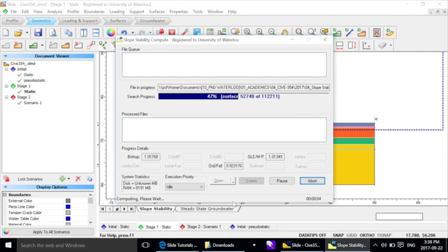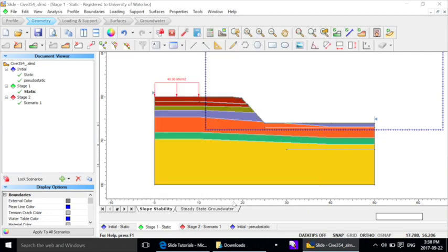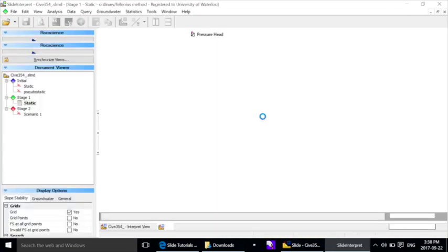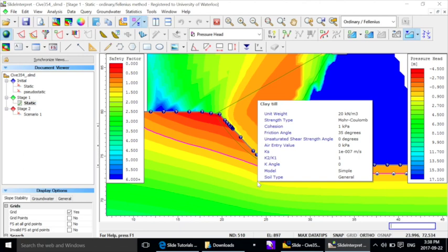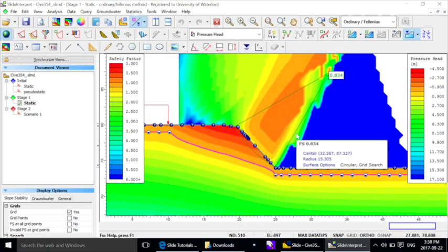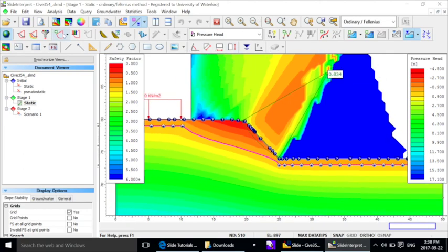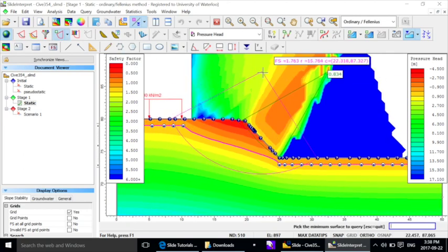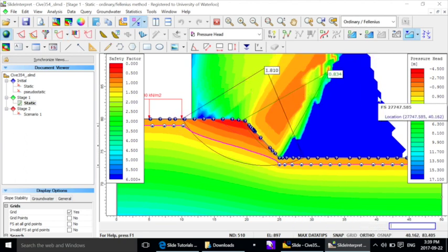So we modify 15 degrees, and we got now 0.85 in the factor of safety. So we are close, okay? But what is important here is to see this failure surface, okay? This is a very shallow surface, but let's think about this surface, for example. If this is the surface, you got at the end 1.5 or whatever, okay?